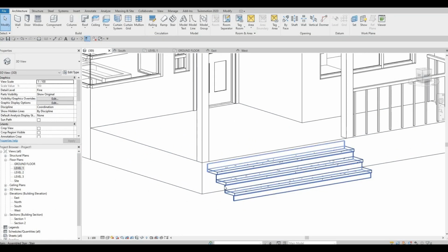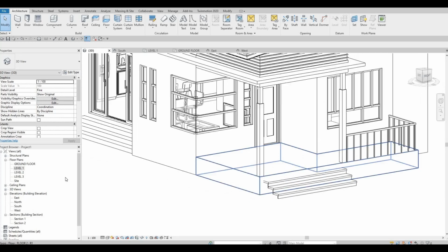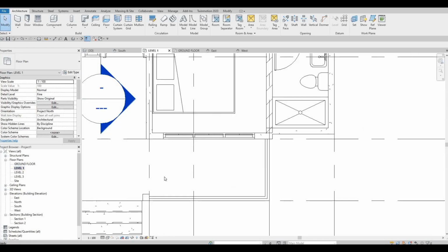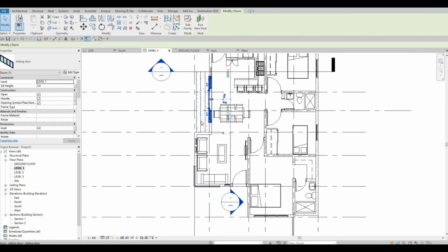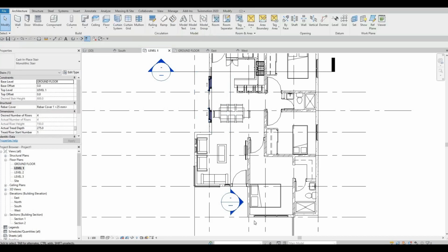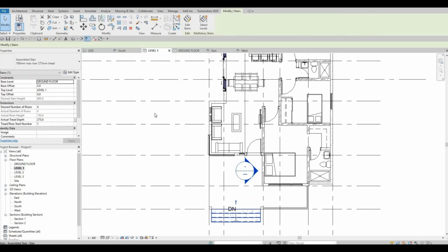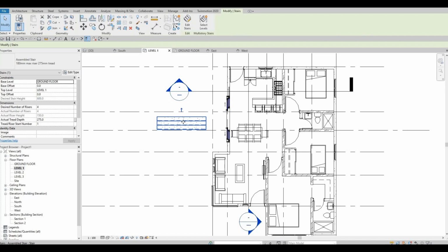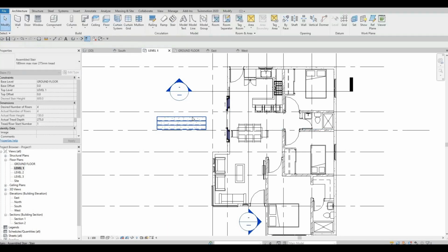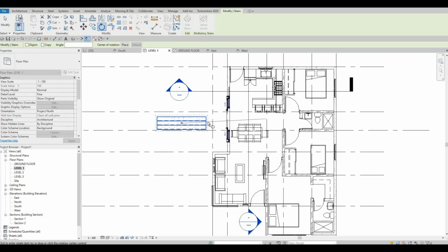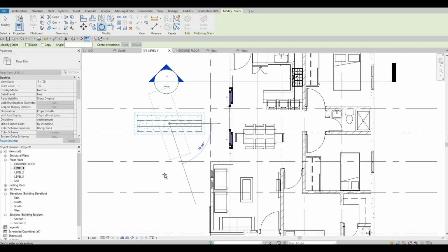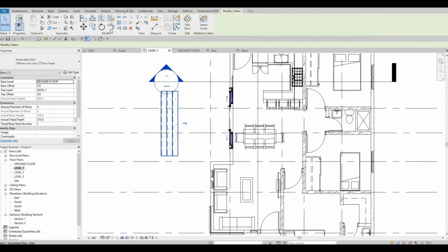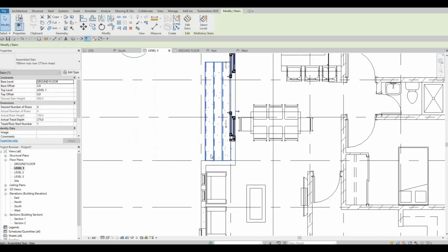And then we're gonna remove this or add something here. And then let's go back here and delete this. And then just copy the ones that we did so that we don't need to recreate that. So copy that, rotate, RO, make sure it's 90 degrees. You can even type it, and then move it, MV, and move it on the corner.